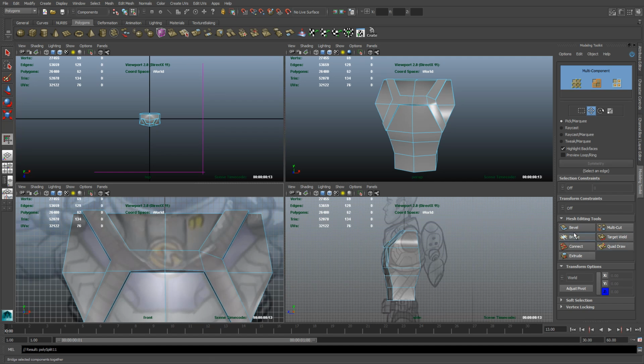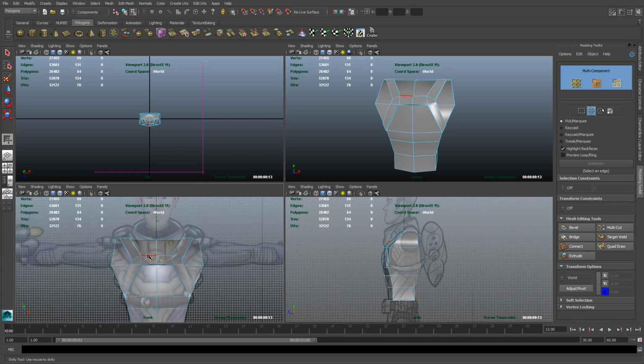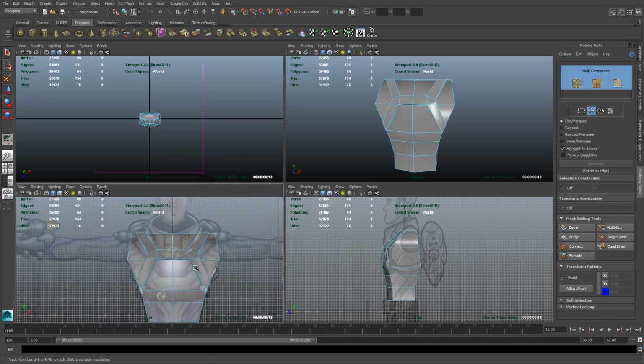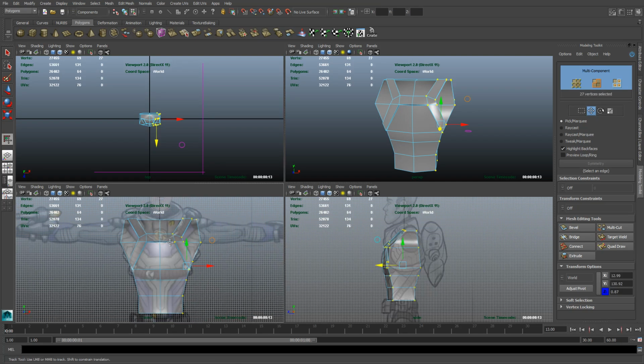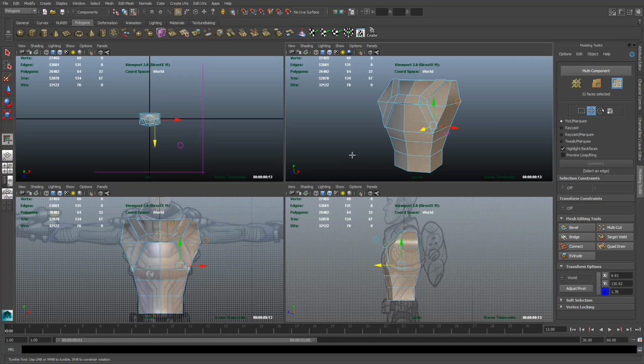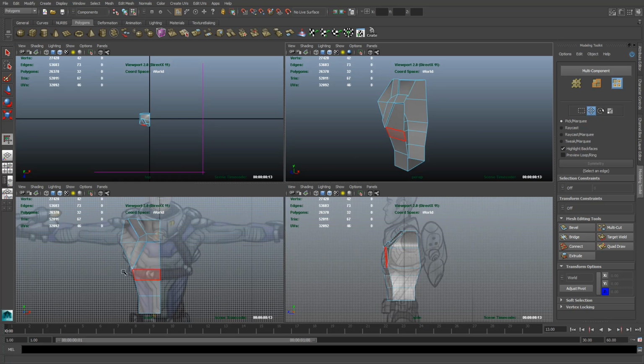Perfect. Let's do the same thing to the other side just to repeat the process. Again, so you can see here what I'm doing is I'm duplicating my work. That's kind of in a production environment, not something you're going to want to do. Normally, by now I would have already cut off this entire side just by selecting all the polygons. Like, let's see, let's go into face mode. So we'll right click and choose face. We'll just draw a box around it, selecting that entire side, hit delete, and now we'll just work with that side.